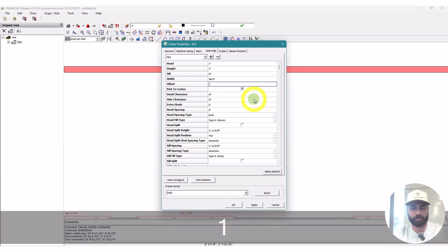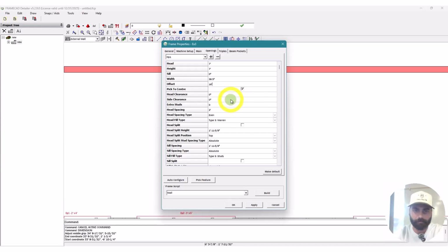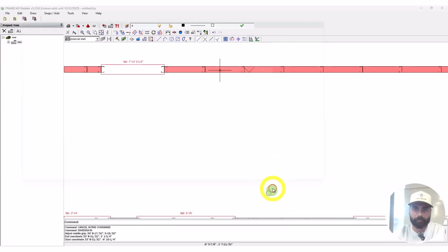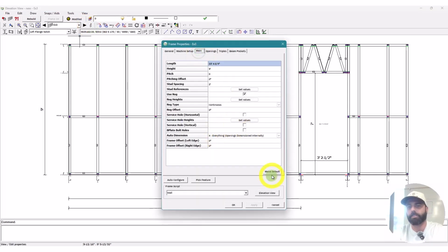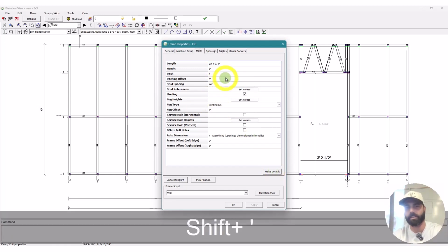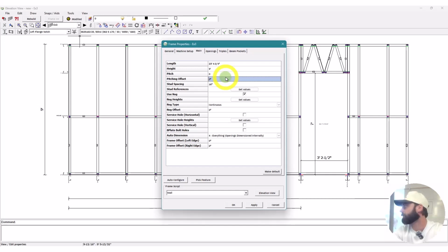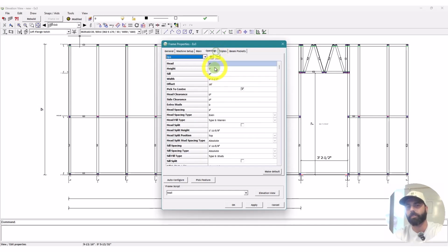So we can go ahead and design this. The other thing too is you can make it your default. That's the one thing that's going to be different with Dev's scripting than ours. So if I wanted everything to be 16-inch centers, or if I wanted all my header heights in a project, on opening 1, if I know that every header height is at 6'10 and a half, when I frame that first opening, I'll make that my default for the whole project based on how many openings are going in.